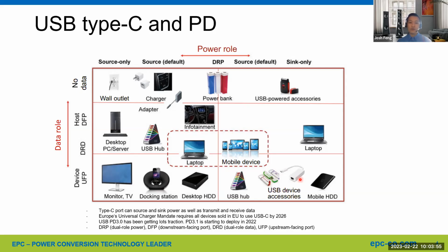As a consumer, it's a huge benefit, because imagine in the future, in 3 more years, you just have one cable that can potentially be used for all your consumer power electronics devices, or even some industrial applications. PD 3.0, the lower voltage, lower current version, has been getting quite a bit of traction already. You might see some adapters advertising 60 watts, 100 watts. Those are typically the 3.0 protocols. Now the 3.1 are starting to take over and deploy in 2022.